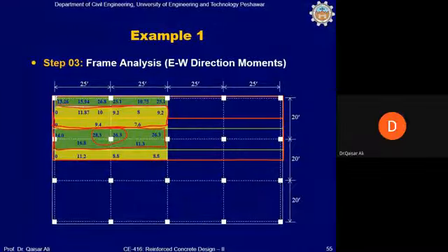And this is the bending moment in the exterior frame. Okay, we have calculated area of steel according to this bending moment, and for the rest of the bending moments, you can calculate area of steel from unit rule, and finally you can also calculate the spacing once you calculate the area of steel. Okay, then finally you will have to make some adjustment in the spacing.